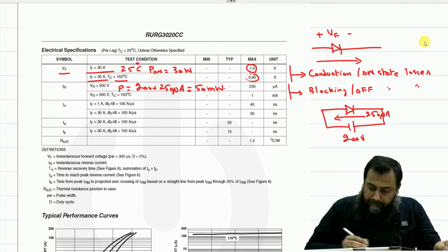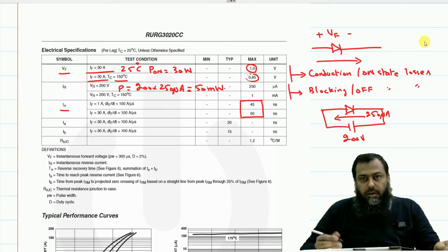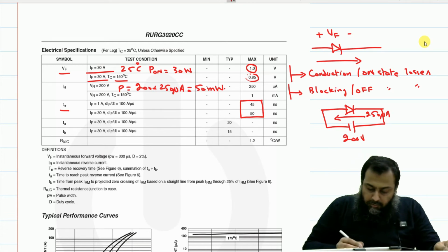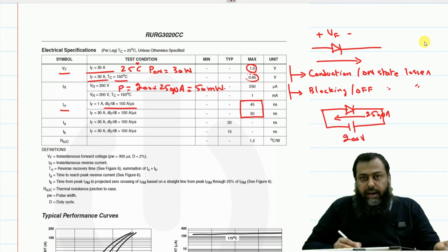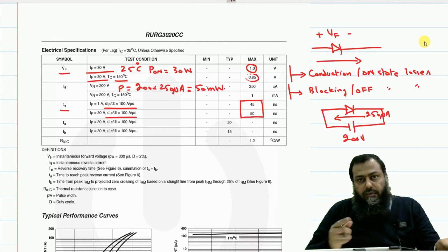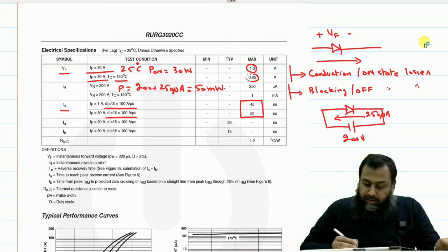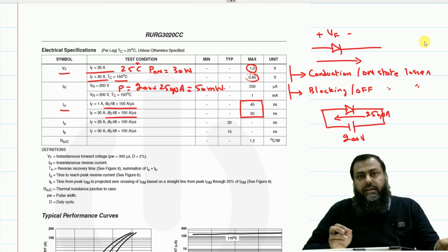Also, we can see here that this reverse recovery time is quite a small time. Therefore, this diode is capable of operating at high frequencies. Notice here that this dIF over dt is set at 100 ampere per microsecond, and it is mainly because power electronic circuits mostly contain inductances, and therefore this is an important parameter that defines at what rate of change the forward current shall actually drop to the minimum value, and therefore it is quite important in defining the peak reverse recovery current of a diode.